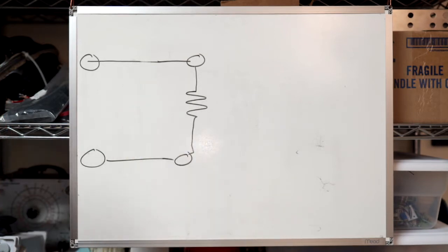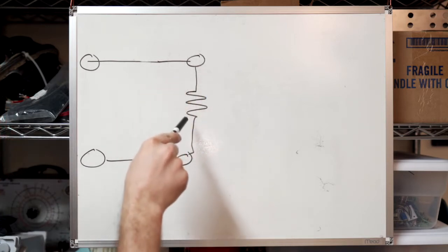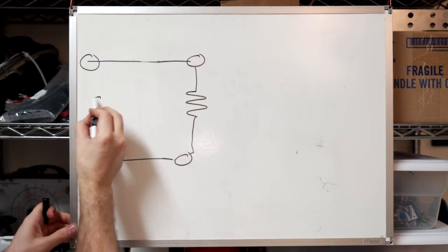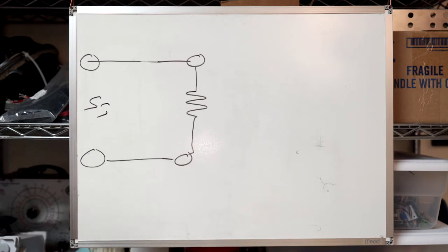What all that means is that they act more like voltage sources, which means they have very, very low output impedances. And so you would actually, before you found the output impedance of a solid-state amplifier, you would reach a value that was dangerous for the amplifier to run at.